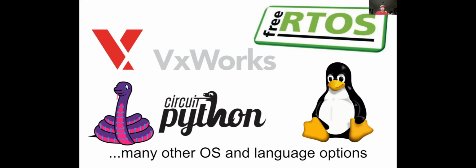So there are two real-time operating system options that people commonly use: FreeRTOS and VxWorks. VxWorks is made by Wind River, but it's closed source, so it's not as good. And then also Linux. Linux is super popular for space because it's open source and easy to work with, which makes it easier to get your stuff done.